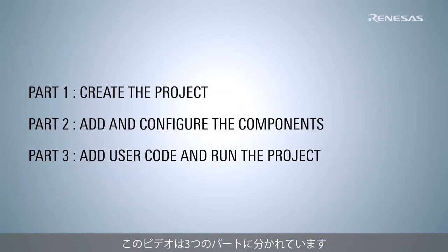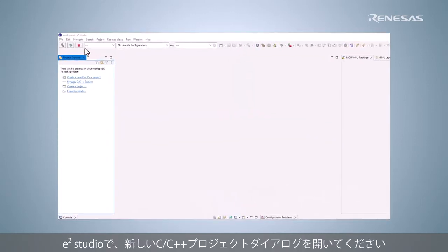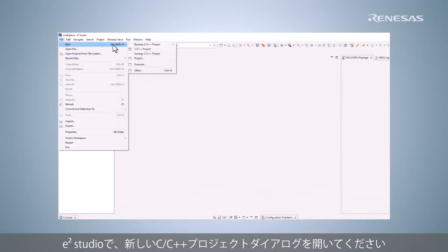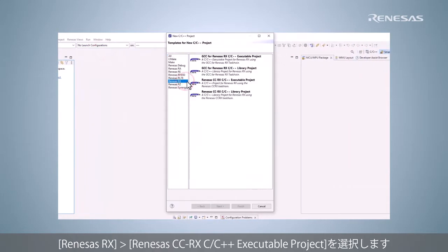There are 3 parts in this video. First, create a Smart Configurator project. In e² studio, open the New C/C++ Project dialog. Select Renesas RX, Renesas CC-RX C/C++ Executable Project.